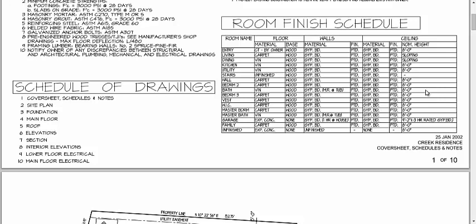So when they say a nominal height is 8 foot, 0 inches, the actual height's probably closer to 8 foot 1 inch, somewhere in there. And we'll discuss in this class as well as other classes why it's kind of an odd measurement. But we say it's an 8 foot wall. So that wraps up that page.